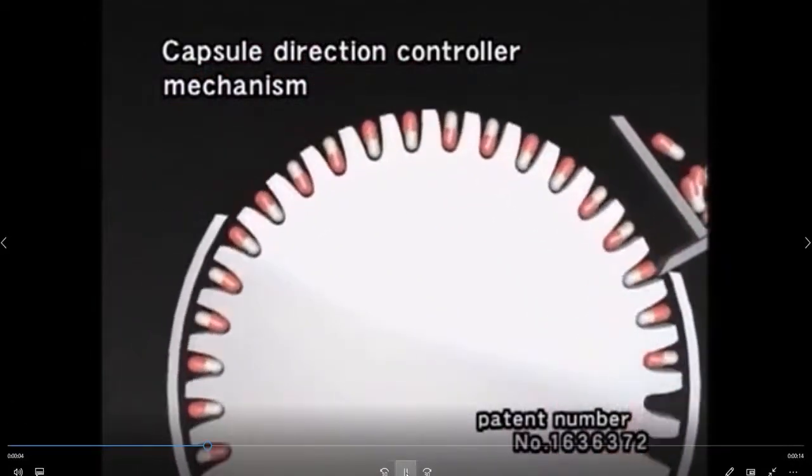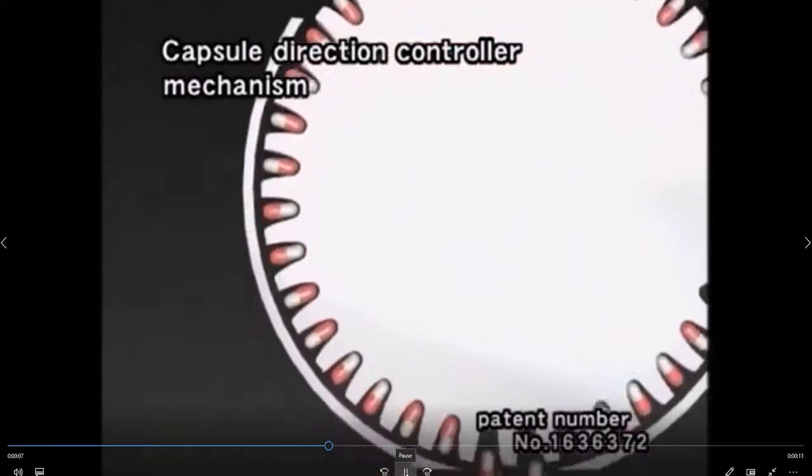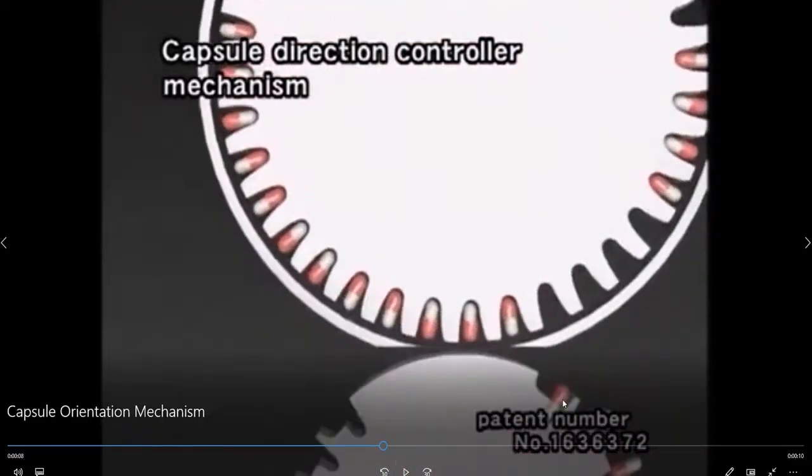Using the difference in diameter between the cap and body, correct rectification is performed. I want you to see this one here because it's important. The opening here can only allow the body to get in, but it doesn't allow the cap to get inside because the diameter is smaller than the cap, but it fits the bodies. So if the capsule comes with the body, it can get inside like what you see here. The bodies will be here and the cap will be at the top.